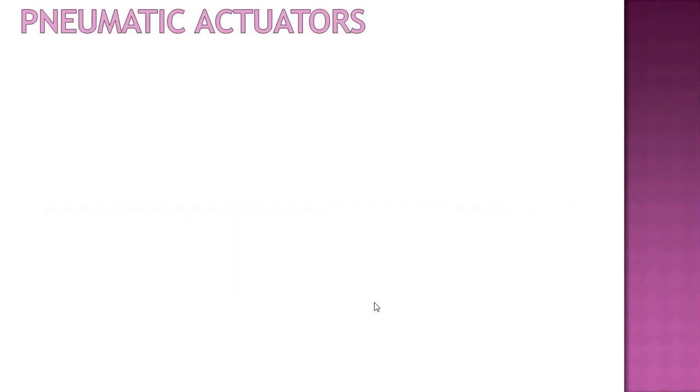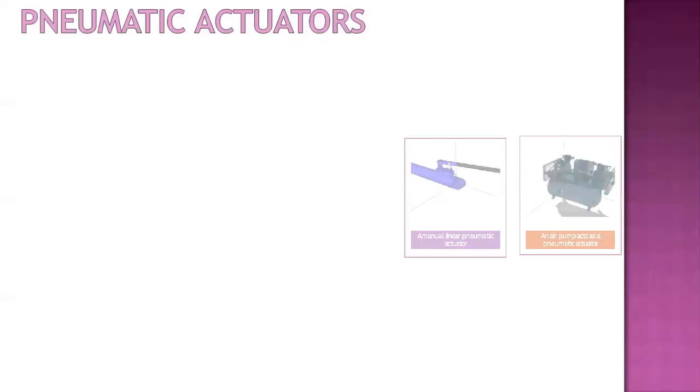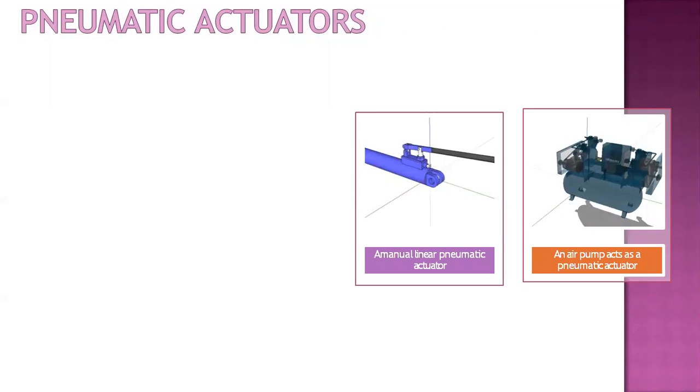Then we are going to discuss pneumatic actuators. Actuators often translate a control signal into a large force or torque as required to manipulate some control element. Pneumatic actuators are most useful for such translation, and the principle is based on the concept of pressure as force per unit area. If we imagine that a net pressure difference is applied across a diaphragm of surface area A, then a net force acts on the diaphragm.